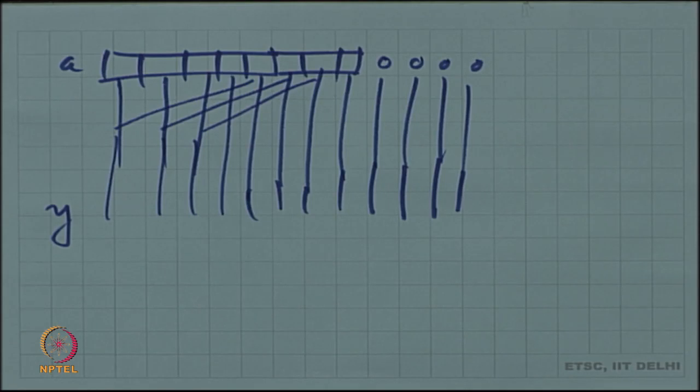In case of a shift operation, we do shift for only the carry flag. So the bit which will be shifted goes to the carry, and the other 8 bits are the same. That means throwing the 0 in from the right side. So again and again, 4 times, we will throw the 0 into the register. So the register will be the same 8 bits only.